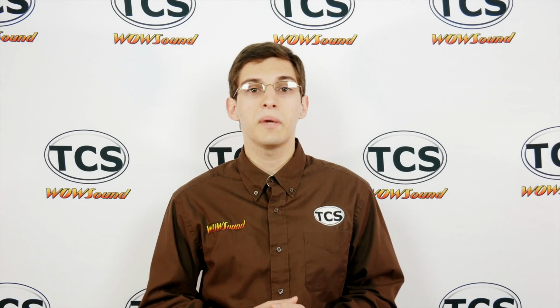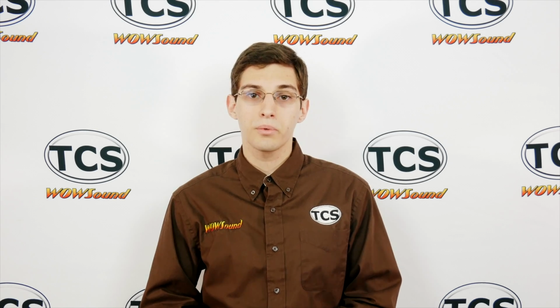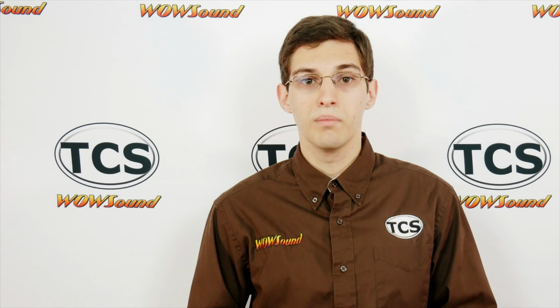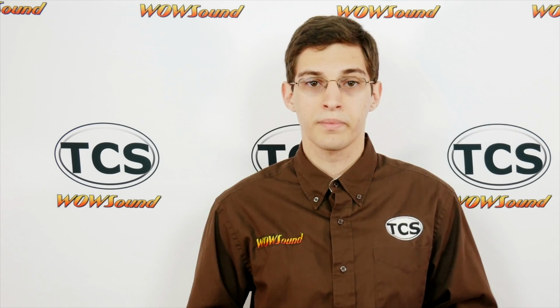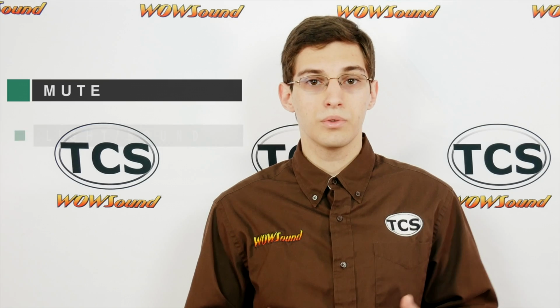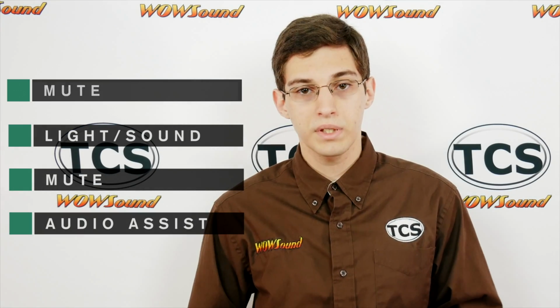Now let's dive into the basics of Audio Assist. To enter the program, simply pick up your throttle and press button number 8 4 times in rapid succession. You may already know that button 8 is also used to mute the decoder as well as switch operational modes. As you press button 8, you will first hear the decoder mute, the transition between modes, another mute, and then you will enter Audio Assist.